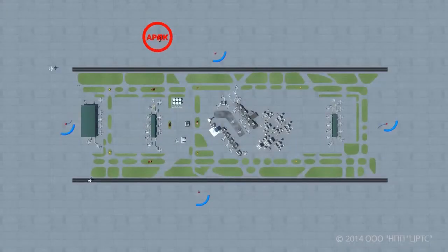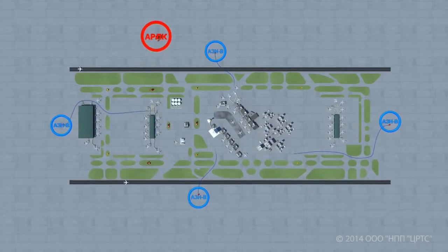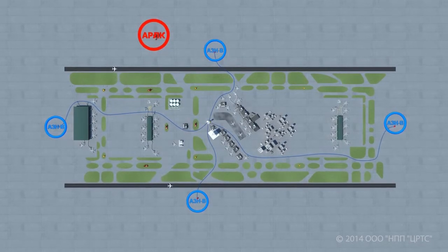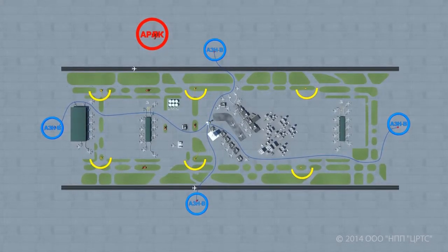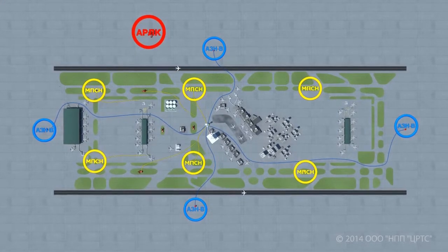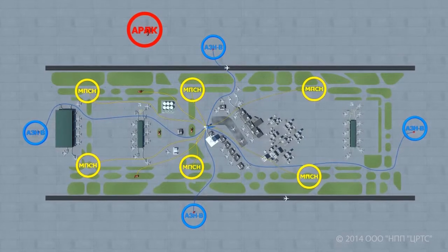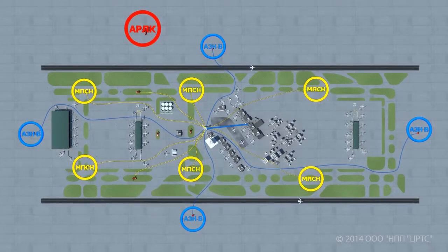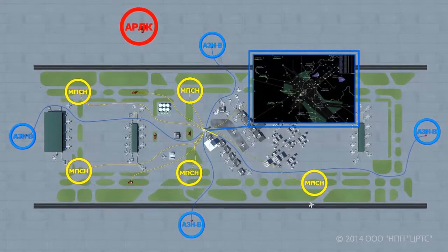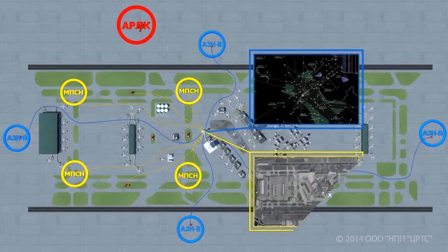One of the most important principles of air traffic management is the integration of all these tools into a single composite surveillance system, which will perform the processing and integration of data from all monitoring tools in a single interface. This composite system of systems will provide surveillance of aircraft in the air and on the airfield. The construction of such a system requires a comprehensive approach based on the principles of smooth transition to the new ADS-B and MSS technologies.